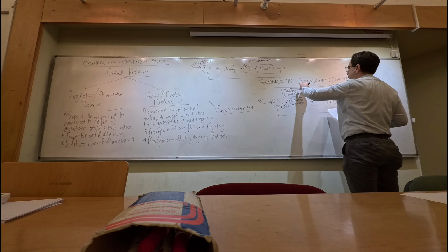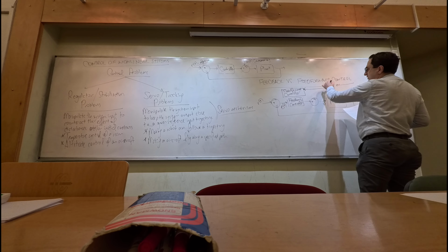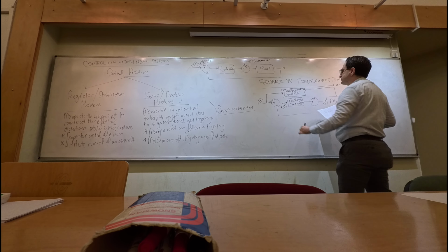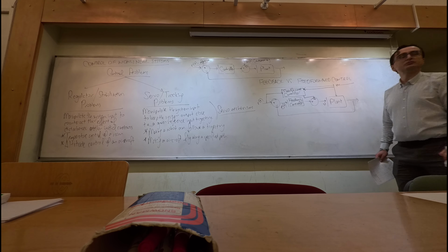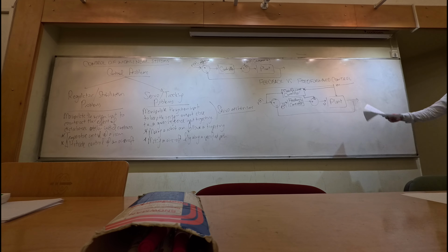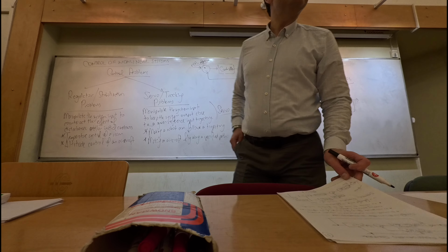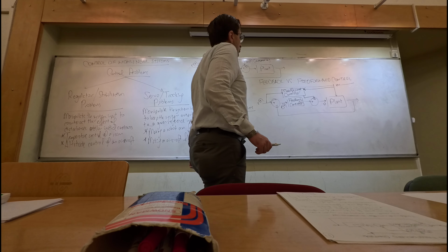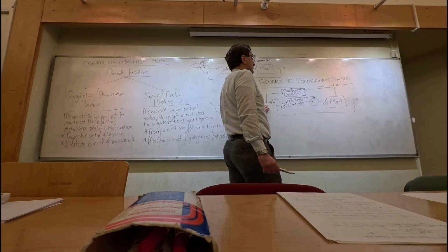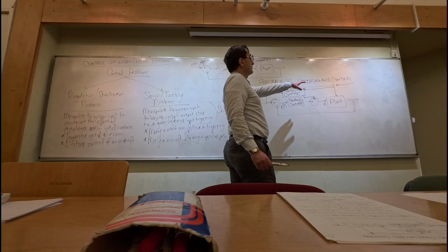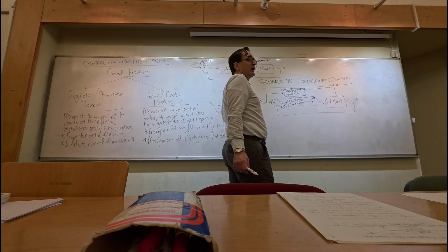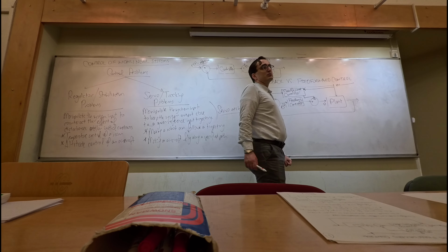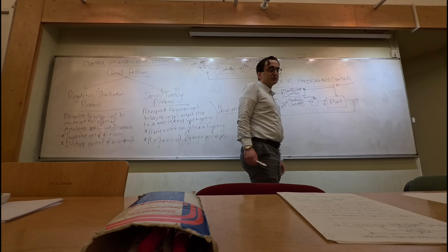And the feed-forward controller has the following structure. In general, a feed-forward controller can get its inputs from either the disturbance or the reference signal, and it would provide its output to the input of the system. That is how a feed-forward controller appears in the topology of control systems. It takes its inputs from the reference signal or from the disturbance signal, and it provides an additional input to the feedback controller in this diagram.